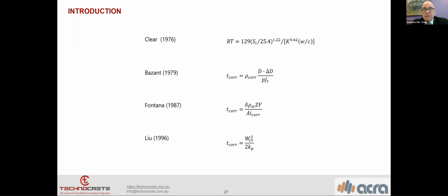Has there been research in Australia about bolting carbon fibre to concrete, or is it always adhered? What other alternate anchoring methods are there? For strengthening? Yes, for carbon fibre strengthening. Okay, we have 3 products for carbon fibre strengthening. We have wrapping, which is fabric, flexible CFRP, and it can be wrapped around the structure element. We have carbon fiber laminate, which is not